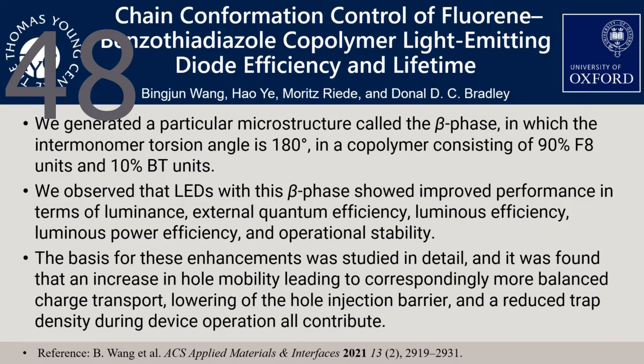Hello, this is Bingjun Wang from University of Oxford. Today I'm happy to talk about our recent work about chain conformation control of a fluorene benzothiadiazole copolymer for improved LED performance and lifetime. We generated a particular microstructure called the beta phase, in which the intermonomer torsion angle is 180 degrees, in a copolymer consisting of 90% F8 units and 10% BT units.